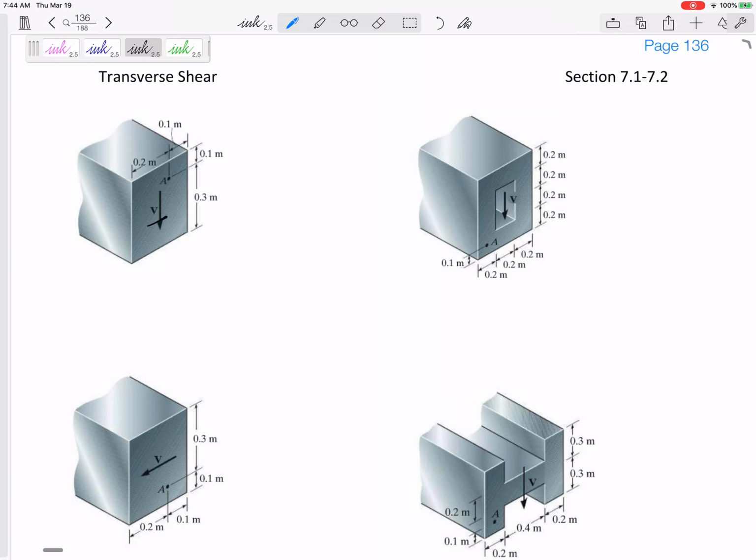So we've got this V right here, and here's my cut. Here's my cross-sectional area. My Q is going to be Y bar prime A prime. I'm going to come back to Y bar prime. What is A prime? A prime would be that area away from the neutral axis. So one thing here. Here's my neutral axis right here.